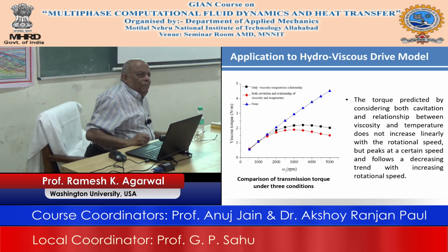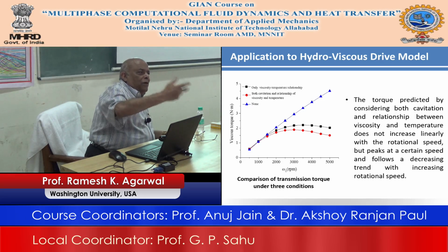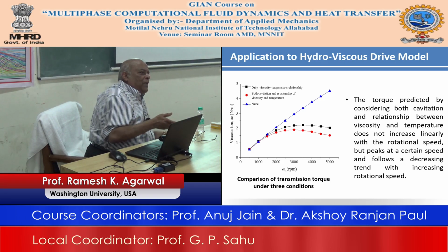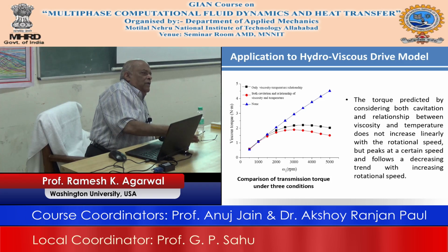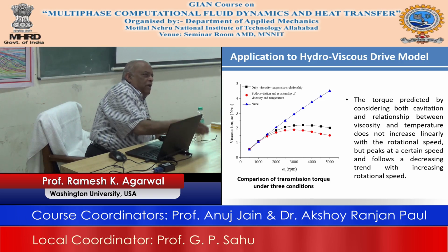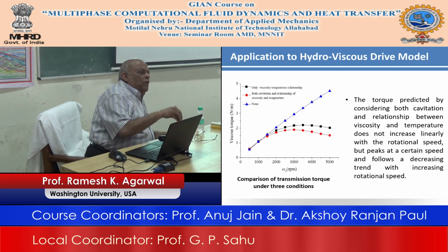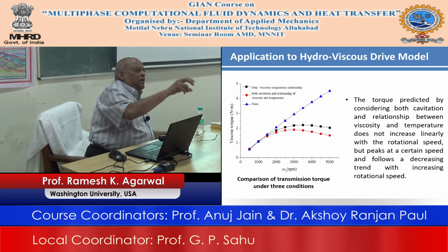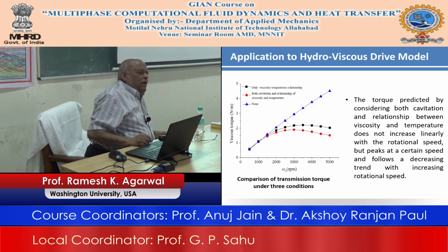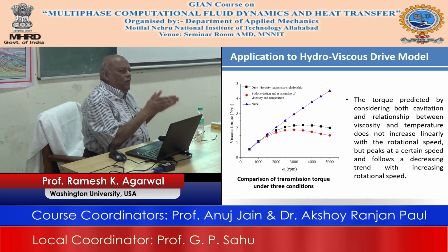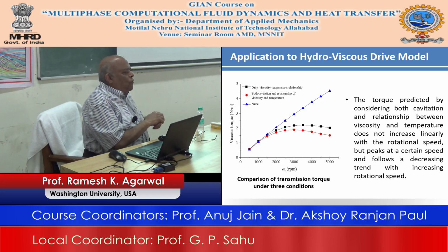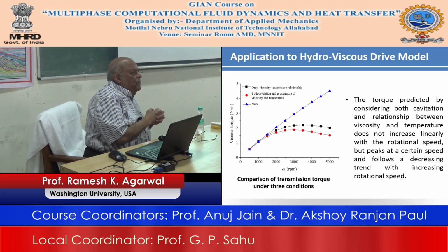When you keep on iterating, the amount of air may keep on increasing because now you have a new set of velocity, new set of information. Then you find that as the amount of air keeps on increasing, the interface keeps on changing. Then the VOF automatically gets kicked in. What does VOF do for you? Nothing more than telling you this is the alpha and this is the 1 minus alpha. So it's a single fluid model, with an alpha to tell you where the air is and where the water is. Is that making sense or not?